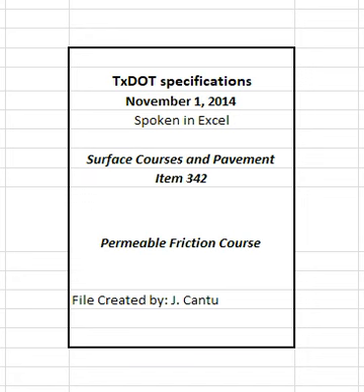If the aggregate mineralogy is such that TxDOT does not yield reliable results, the engineer may allow alternate methods for determining the asphalt content and aggregate gradation. The engineer will require the contractor to provide evidence that results from TxDOT are not reliable before permitting an alternate method unless otherwise allowed. Use the applicable test procedure as directed if an alternate test method is allowed.